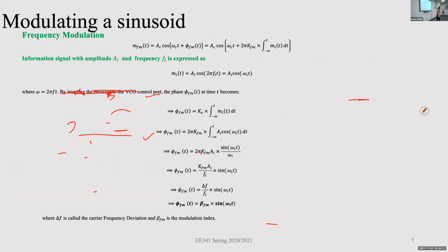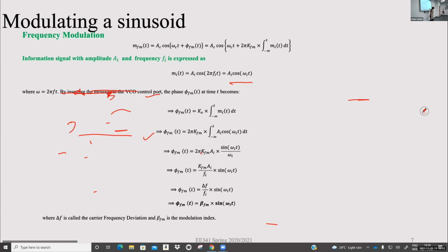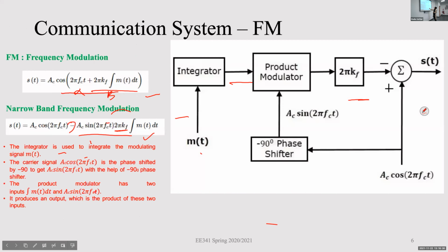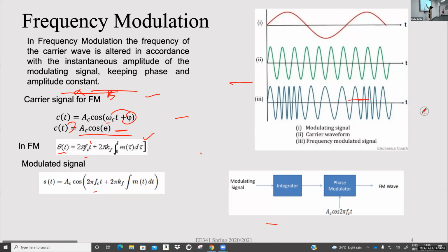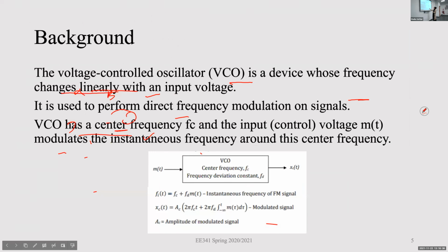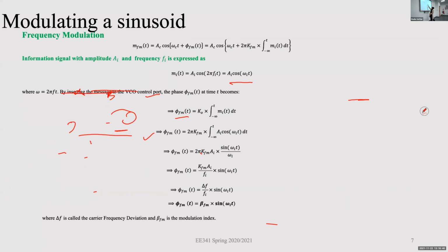So this is my equation for the carrier signal. This I got in the first slide, the first equation. Now I have my message signal. m(t) is equal to Am cosine of omega m t. This we were doing in the previous 2 classes. Then this phi m of t, you remember here. So this is the phase shift. Okay. So this phi is equal to k naught into the integral of the message signal with respect to time. So this is my phase shift.